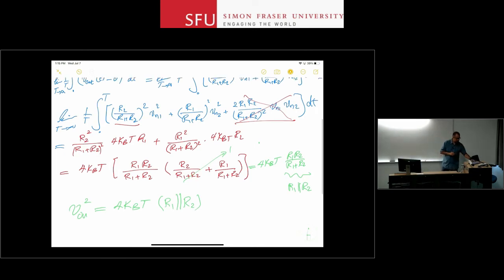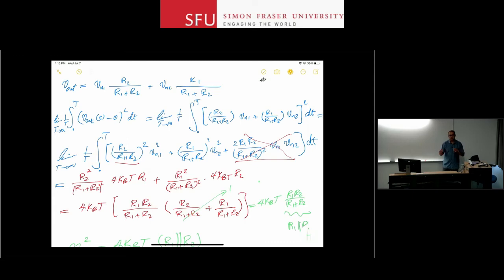The other thing that I noticed is that, when I'm calculating the effective noise of independent noise sources, any cross-product term will be 0. So at the end of the story, it's as if you're calculating the noise of the first one, the second one, and you only keep the squared terms, the variances at the output. Any cross product will go away.